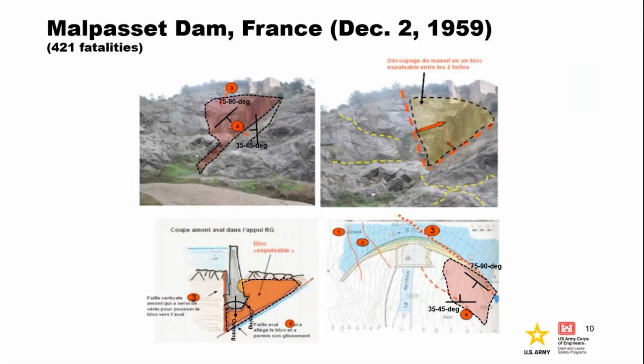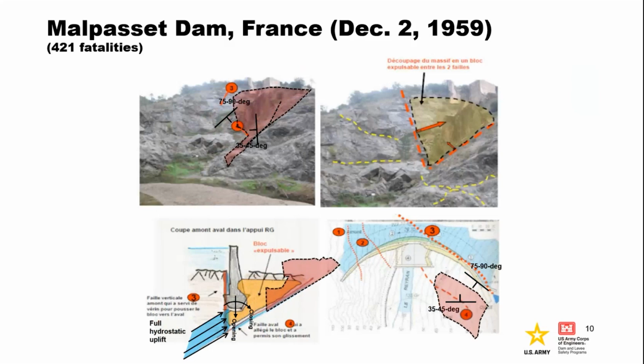And tensile and shear stresses at the upstream face opened the foliation shear and allowed water pressures to easily penetrate to great depths. So basically, the force on this dam caused any jointing downstream to close and jointing upstream to open, and so water was able to get in, basically putting extra pressure on the dam. In addition, there were clay materials along that downstream shear that also created a dam that increased that force.